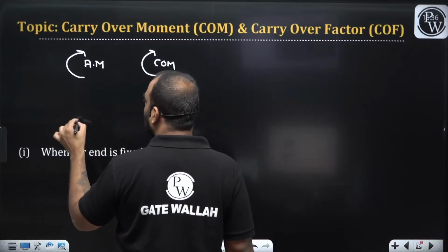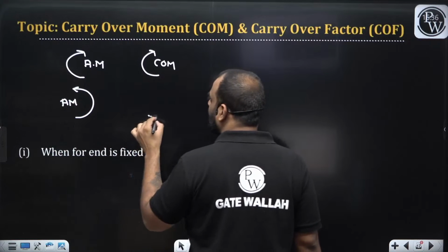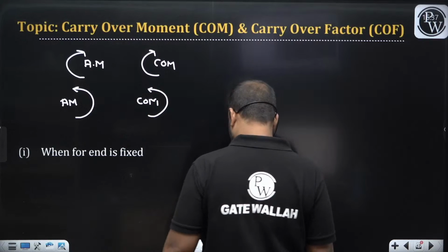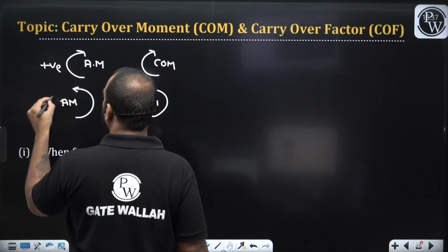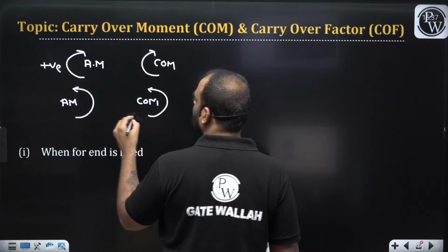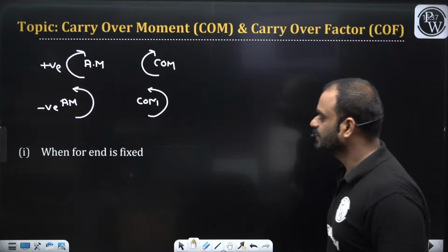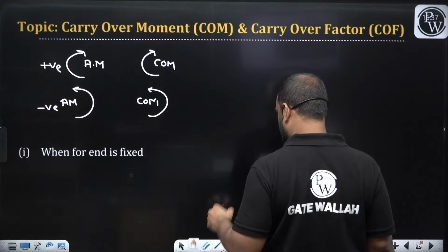If applied moment is in anti-clockwise direction, then carryover moment will also be in anti-clockwise direction. Usually we consider clockwise moment as positive and anti-clockwise moment as negative. Clear?